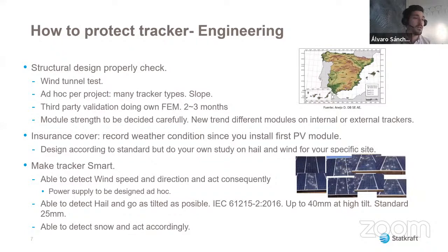They mentioned the IEC 61215 of 2016, which is the standard module suppliers use to check how much load the module can support. So we have seen, just as an internal conclusion, that the module can support up to a 40 millimeter diameter ball or ice ball with a very high tilt.